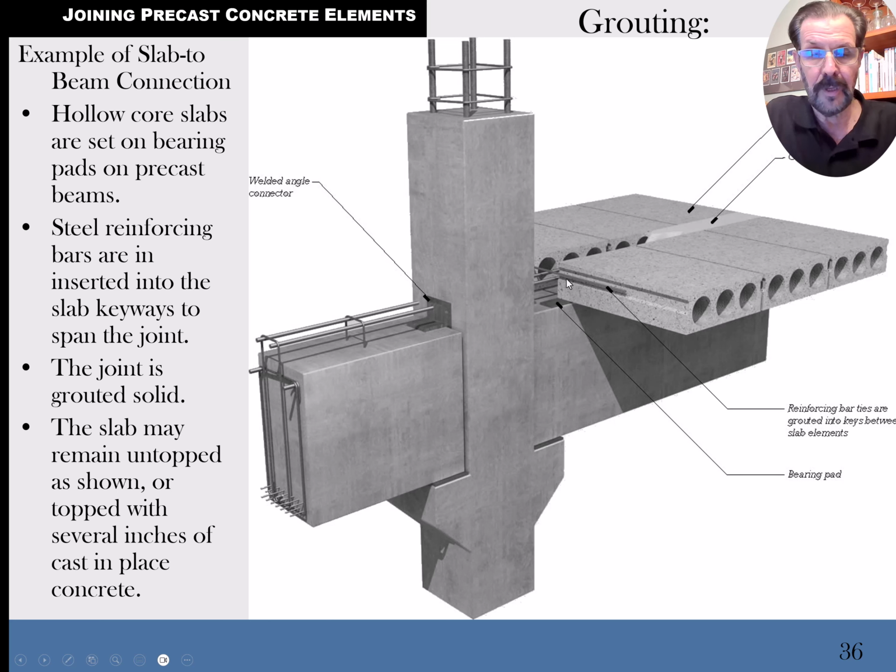But if you have wood or steel, then you only need 1.5 inches of bearing. That's a general rule in construction. 3 inches of bearing for concrete on concrete or on a concrete ledge or whatever. But if it's wood or steel, then you only need 1.5 inches. Anyway, so they've got that here. It's sitting there, it's fine.